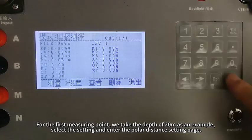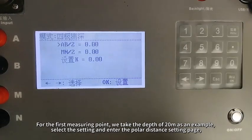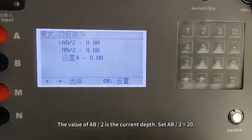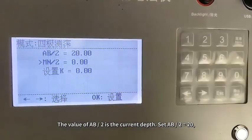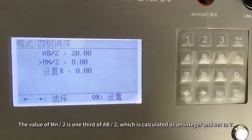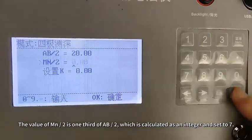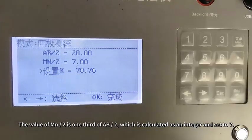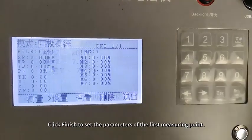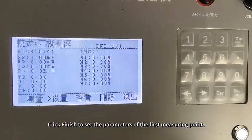Select the setting and enter the polar distance setting page. The value of AB/2 is the current depth. Set AB/2 equals 20. The value of MN/2 is 1/3 of AB/2, which is calculated as an integer and set to 7. Click Finish to set the parameters of the first measuring point.